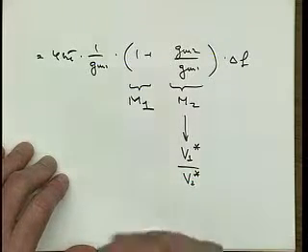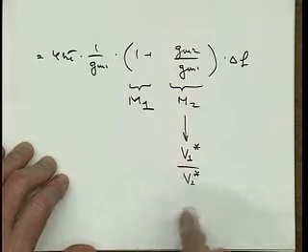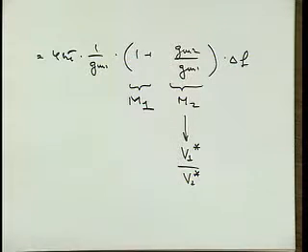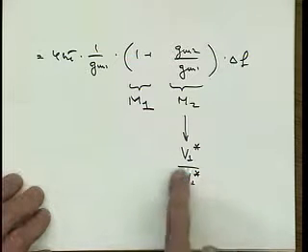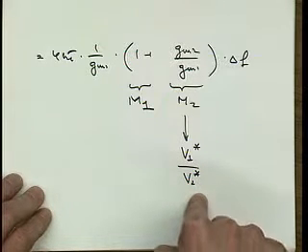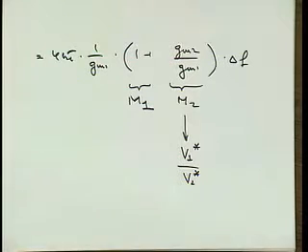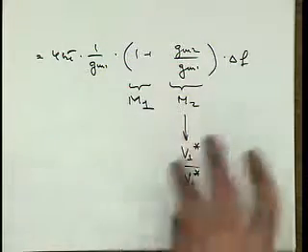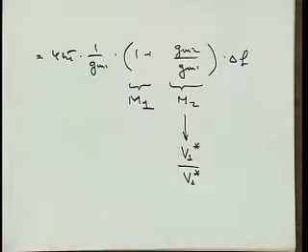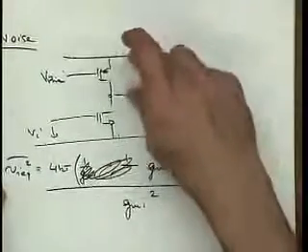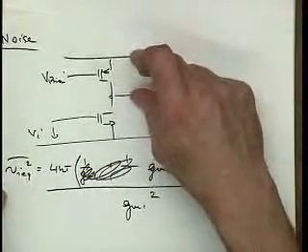If we look at this, that apparently implies that we need to throw voltage headroom at this problem. In particular, it says that V2 star should be large, and more specifically, large with respect to V1 star, at least as large, or maybe a little bit larger. Of course, when we design, that is a compromise, because making V2 star large means that our signal cannot be as large anymore.